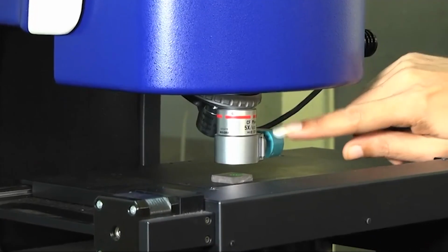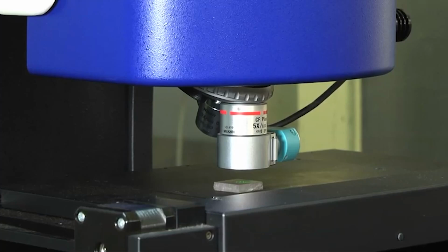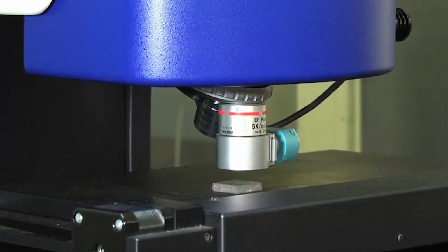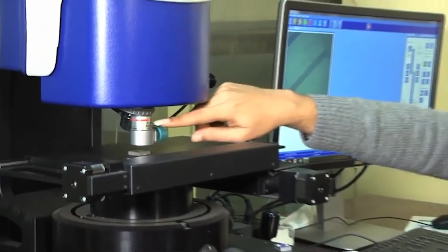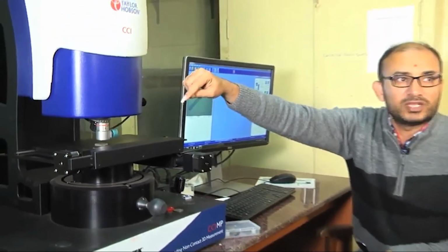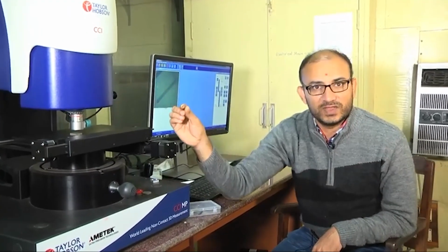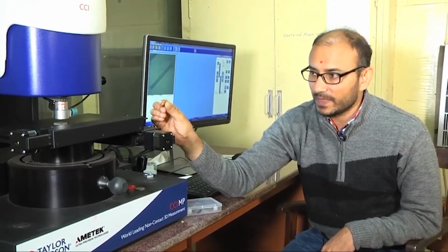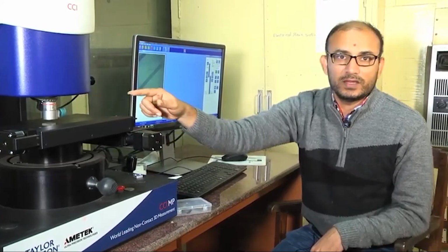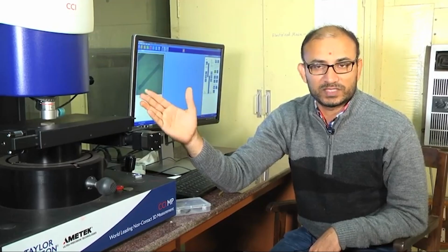Here is how you can select between these two. Suppose your surface has a very big measurement range, say 1 millimeter or 5 millimeters, and you want to capture everything in a single measurement. It is better to go with the 5x, because 5x has a measurement area of 3 millimeter by 3 millimeter. If you have features which are very small and you want to capture small details, then you can use the 20x. We have two different magnification lenses here, but there are many ranges; you can start from 2x magnification to 100x magnification depending on your requirement.